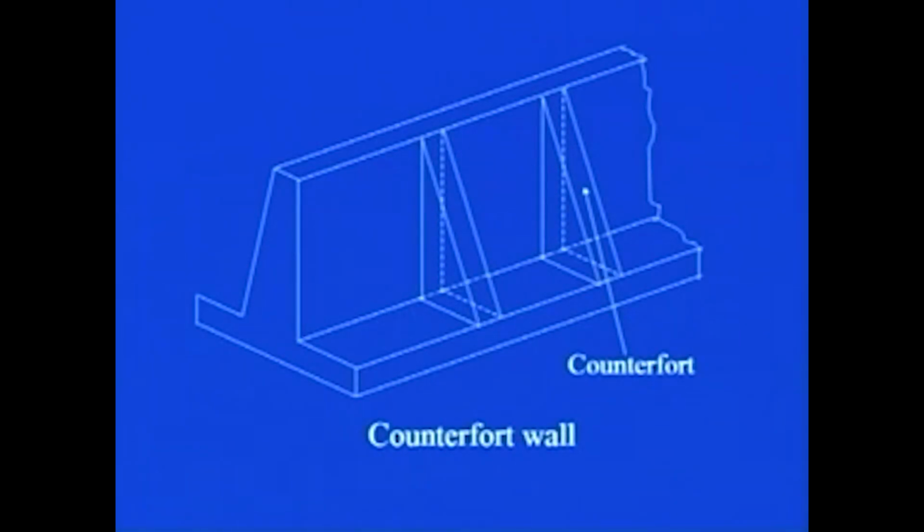After that, if the length of the wall or the height of the soil to be retained is too much, then going for a cantilever wall causes very large magnitudes of bending moment and shear forces on the stem part of the wall, which causes very big sections in design. So, to avoid all these problems, counterforts are provided at certain intervals to provide rigidity to the stem part of the wall.